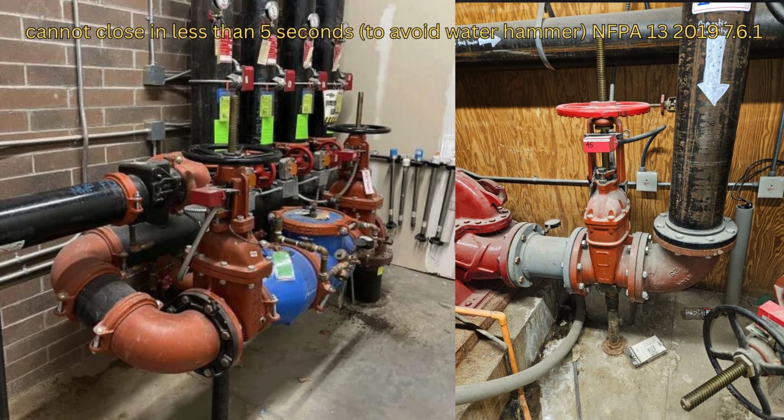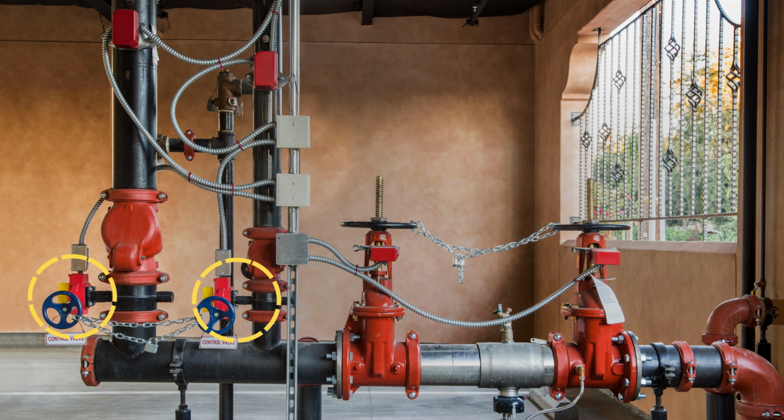Major control and isolation valves in traditional fire sprinkler systems are typically large gate valves of the outside screw and yoke, OS and Y type, sometimes called rising stem valves. The state, open or closed, of this type of valve can be determined at a glance, and specialized locks and alarm sensors may be attached to restrict and monitor the settings of these valves, which are critical to overall building safety. Newer systems may use butterfly valves instead of some or all possible OS and Y valves.